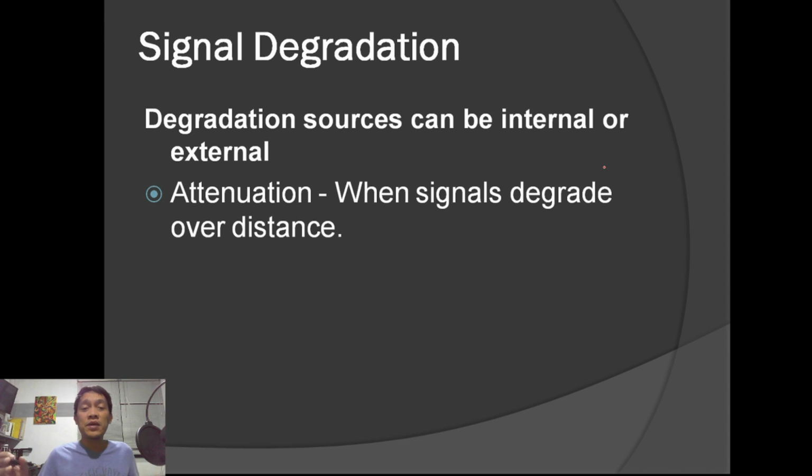Okay? But sometimes in reality, we've tried extending on a longer cable exceeding 100 meters. So, minsan magkakaroon, pero that's a problem when you extend beyond 100 meters. Minsan magkakaroon, tapos mapuputol-putol na siya. So, basically, because of the attenuation, the signal degrades over distance. Okay, so that is attenuation.